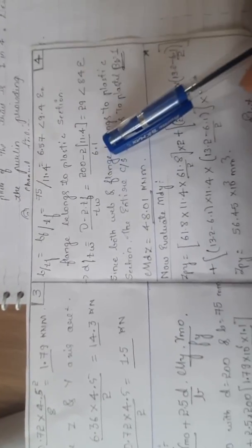So in order to check for flexure your design equation has to be satisfied. Okay, so the design equation happens to be Mz by Mdz plus My divided by Mdy should be less than or equal to 1. So for Mdz, the formula is beta b ZPZ Fy by gamma m0, limited to 1.2 Zez Fy by gamma m0. So here you are considering it as laterally supported. So in order to finalize your beta b you will have to classify the flange and web sections.